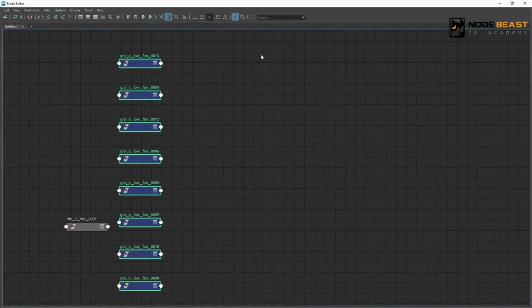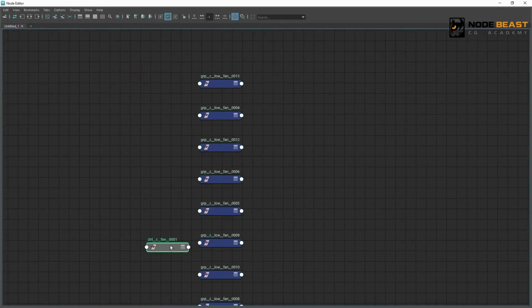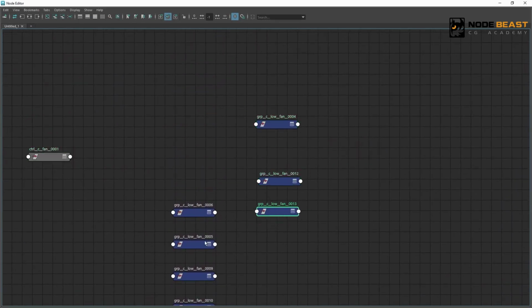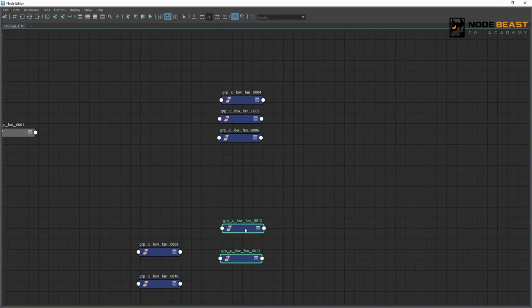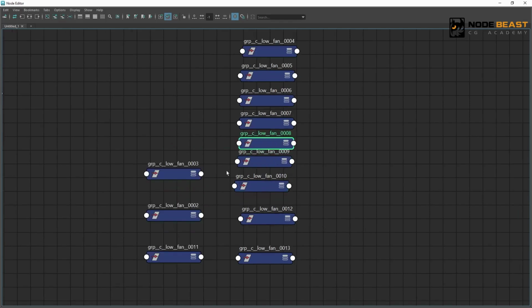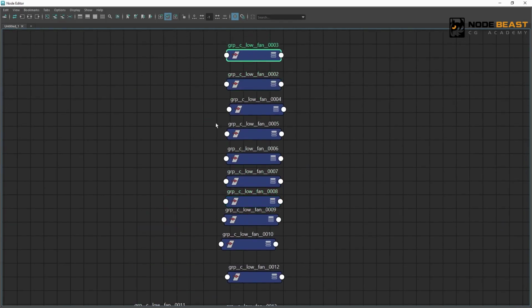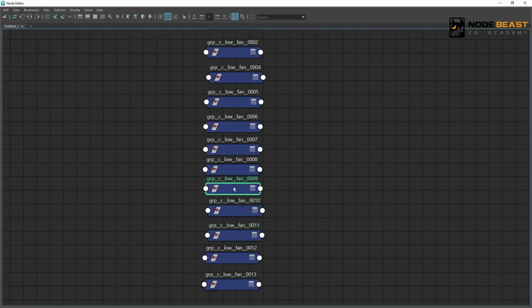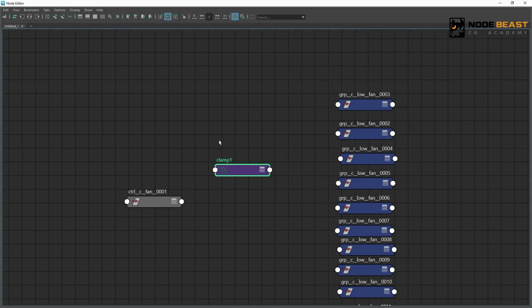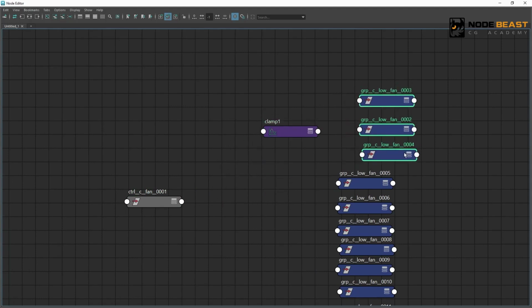There are quite a few things here, so I'll maximize the node editor window and arrange them. This way, we've arranged them in order. We'll connect them one by one. Let's first create a clamp node. Because clamp itself has three values, R, G, and B, to save on nodes, we can use one to control three fan blades, because each one only needs rotate Z.